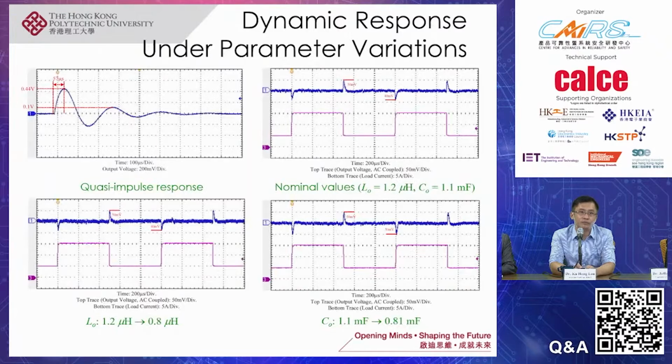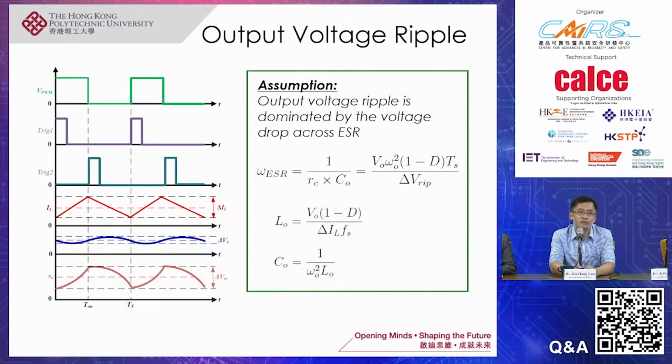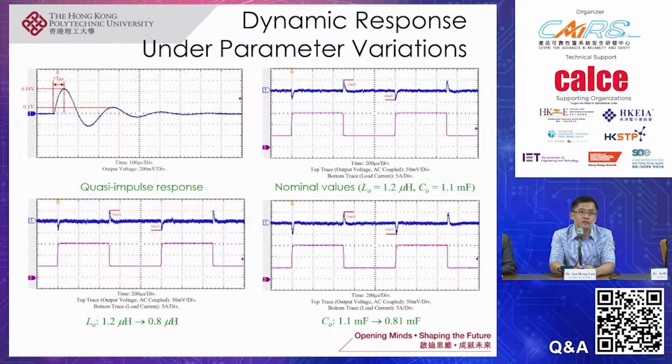After implementing the proposed, we call it auto-tuning controller, because after obtaining the values of the two critical frequencies, we can update the controller. In front of you here is the test we have done on the buck converter implemented with the auto-tuning controller. The first figure on the top left is the impulse response. We measure that at the converter's output, and then we use this information to estimate the resonant frequency of the buck converter, or of the second order filter.